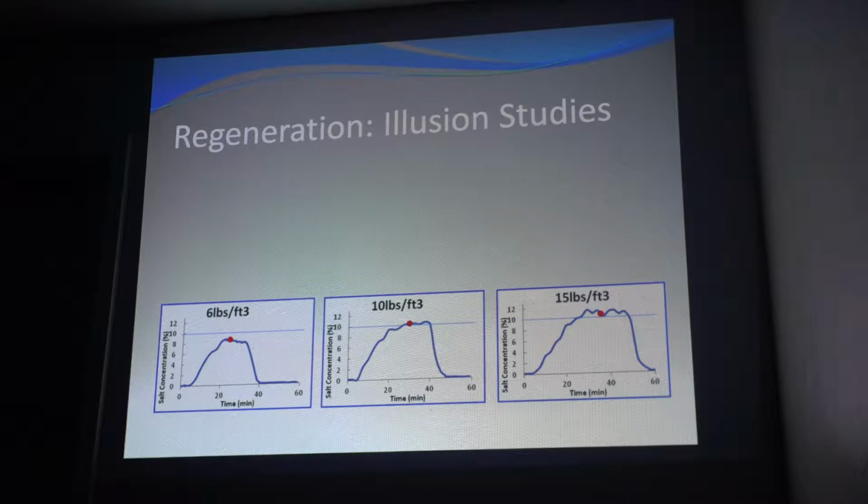But then you get into a car wash, which would be the next one, where you want a higher resolution soft water. You want to be hovering in that 2-3 parts per million range. So you're going to want a higher percentage of brine in your elution study, and hang on to that.